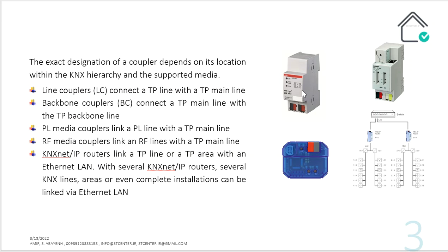Backbone couplers, BC, connect the TP main line with the TP backbone line. As hardware, the backbone coupler and line coupler are the same, okay? We use the same hardware, but when you choose the right physical address, you make the difference between the line coupler and backbone coupler.